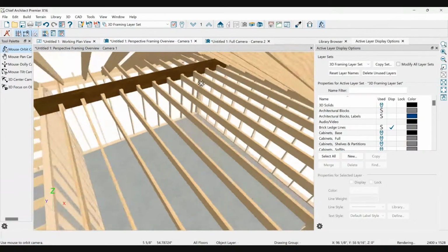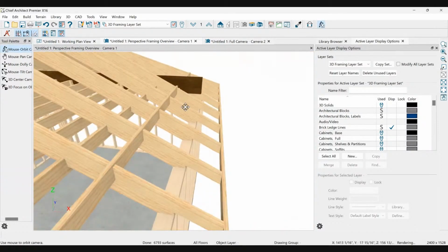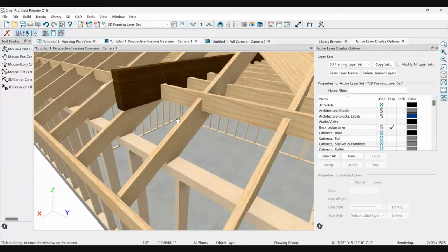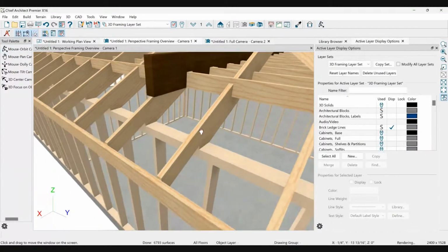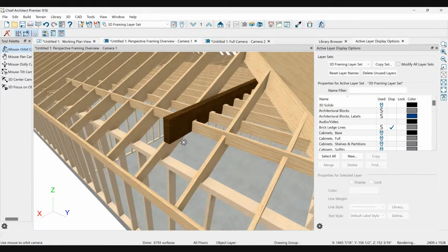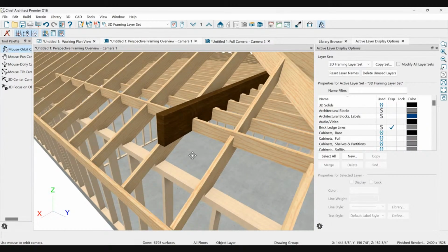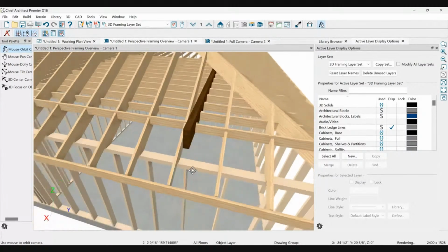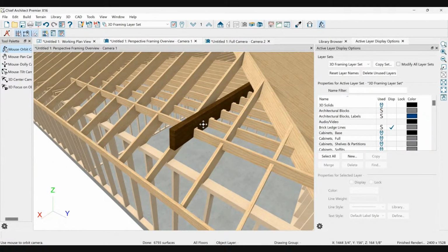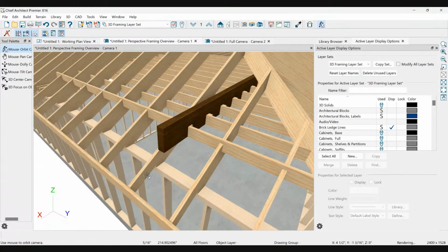That's fine. But take a look at this side. What is the problem here? You see what's going on? Now my beam's too high and my roof, like this wall didn't change because this is a 9-foot wall. So unless you're willing to do some ridiculous, crazy engineering detail to make this joint stiff enough to hold the weight of the beam, you cannot put a beam, you can't run a beam into a sloped ceiling end like this.